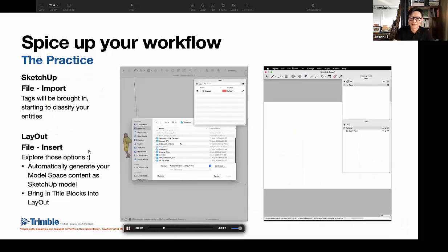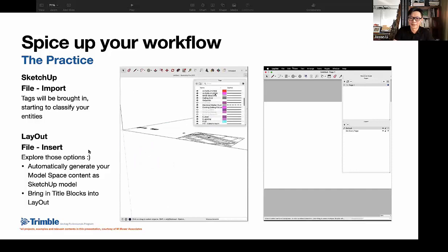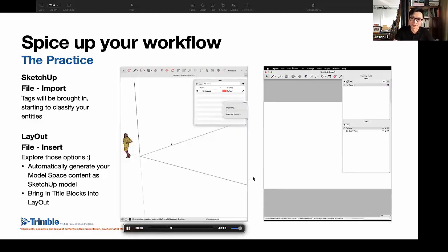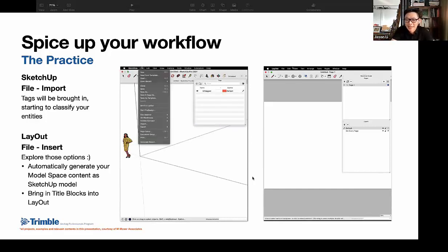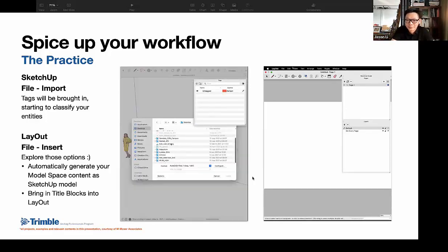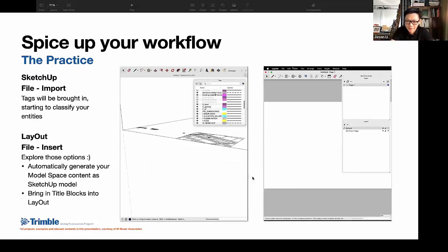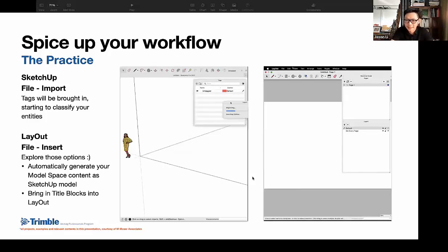And I know until here, a lot of people may be wondering how can I set up a system like a tagging system plus a layout template? That's pretty difficult, right? So actually, the easiest way is just you have a CAD, right? And whatever you previously worked with, which is a successful example, you just import the CAD, and all those kinds of layers and information will be brought into SketchUp, all right?